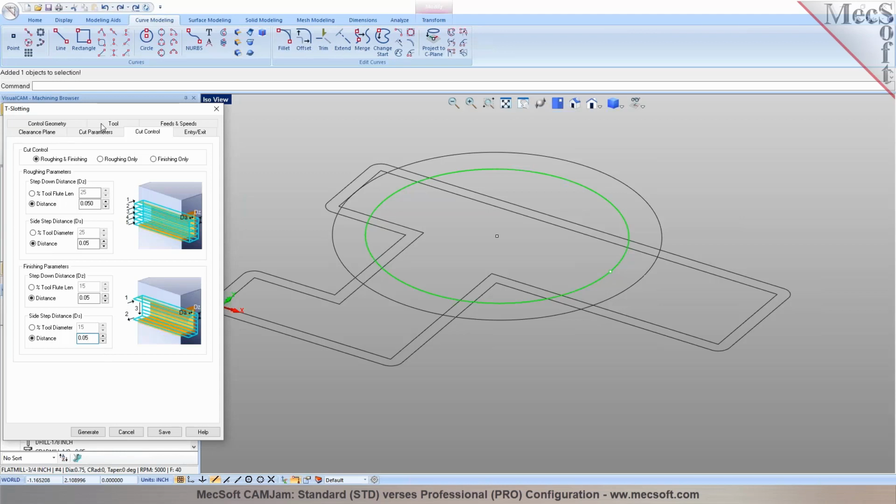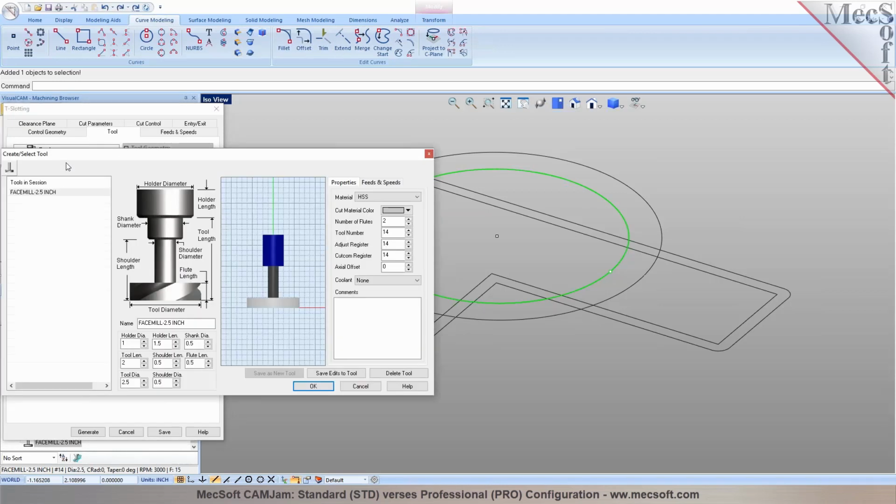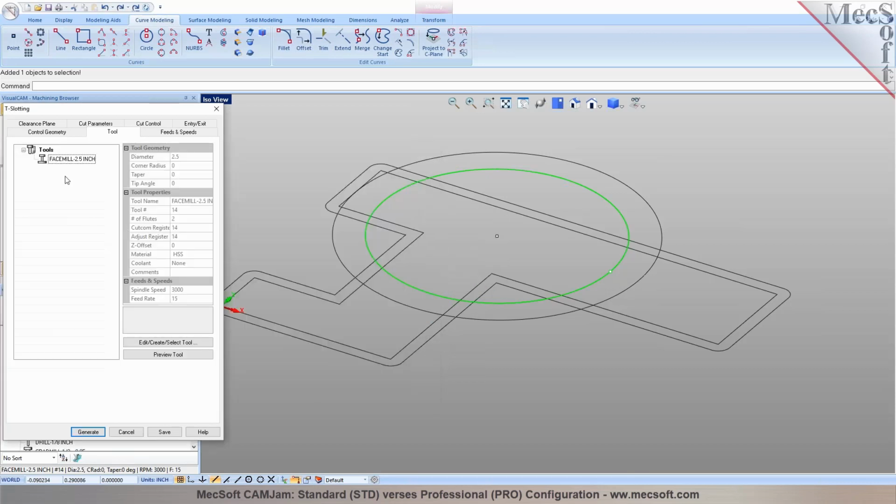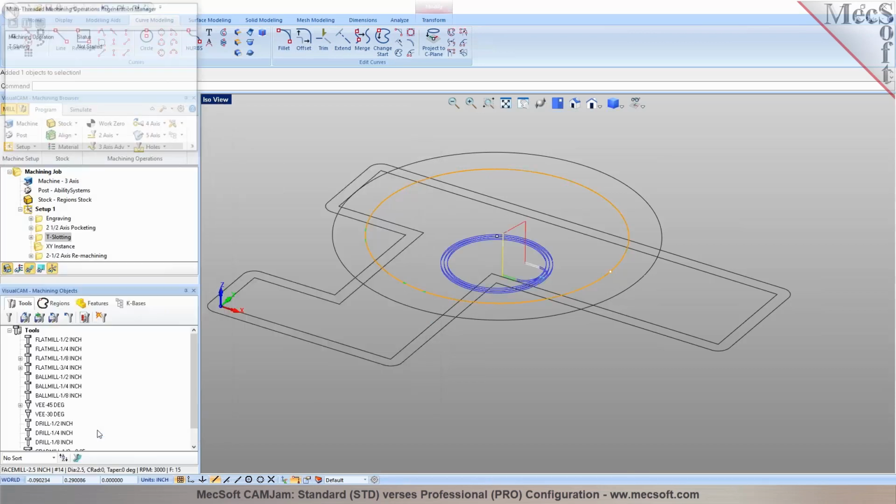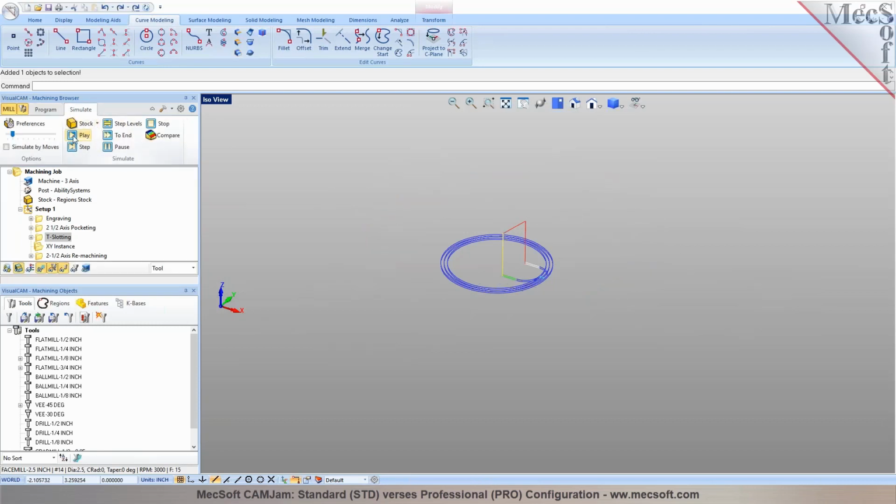And over here, I'm going to pick a tool, a face mill cutter, and I'm going to reduce the shoulder height. I'll just put in 50,000, the flute length of the cutter itself. It's very small, right? As you can see here, I can make it 100 thousandths, so it's at least visible in here. I'll put in 100 thousandths, save it as to the tool. So with this selected, when I generate the toolpath, it actually figures out the T-slot cutting operation.